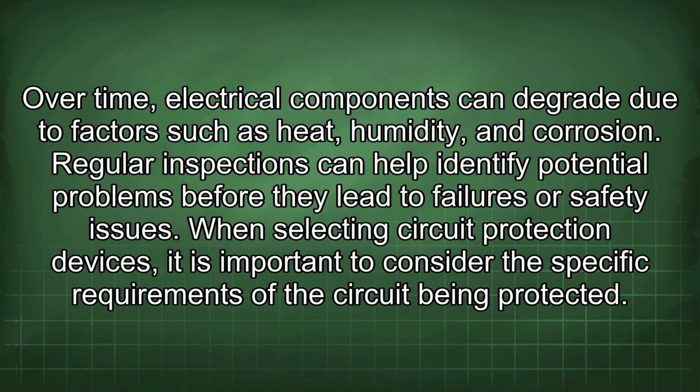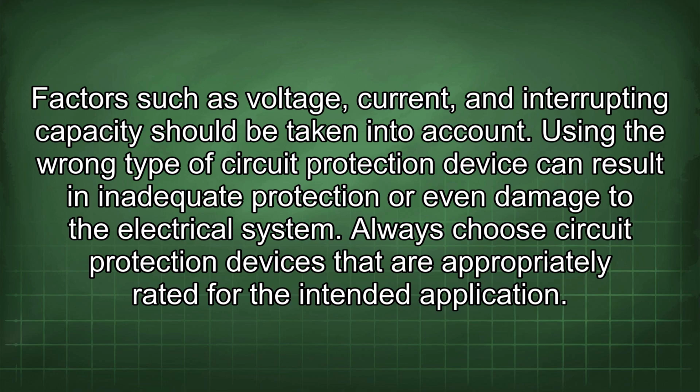When selecting circuit protection devices, it is important to consider the specific requirements of the circuit being protected. Factors such as voltage, current, and interrupting capacity should be taken into account. Using the wrong type of circuit protection device can result in inadequate protection or even damage to the electrical system. Always choose circuit protection devices that are appropriately rated for the intended application.